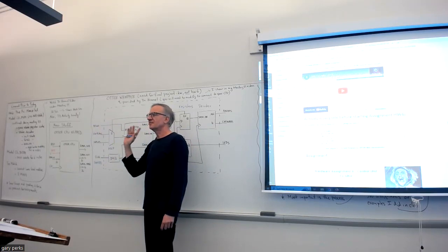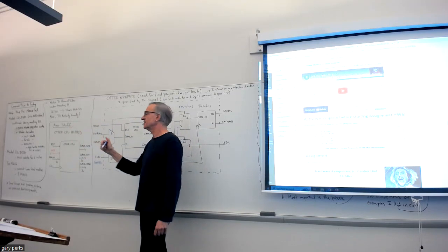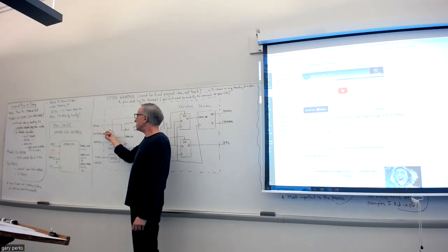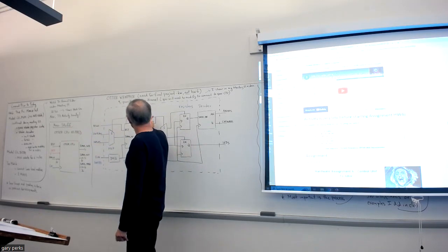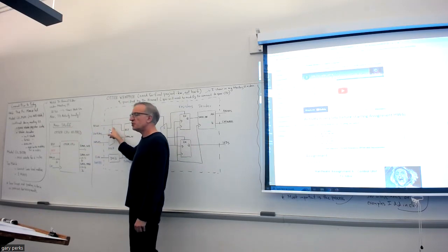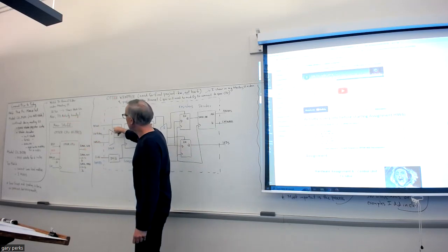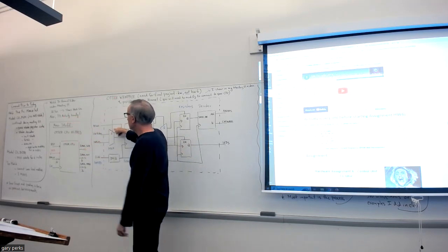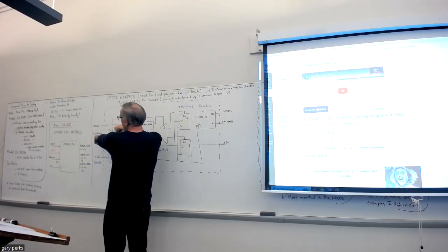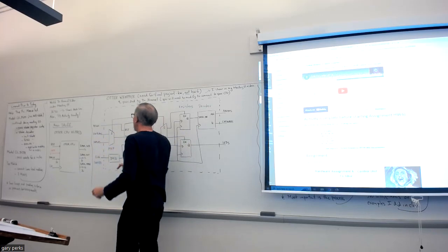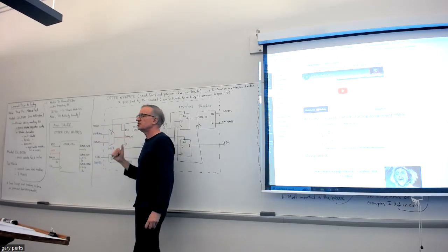I think it's all zeros, right? Yeah, so to choose the switches on this address bus would be hex 11 all zero. Okay, that's what we would have on this select line. And that would connect the switch input to this output that goes into the CPU IO bus in. So the switch data goes into your CPU.